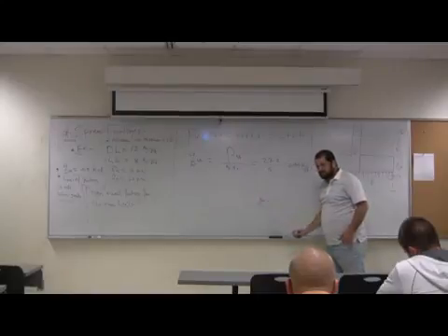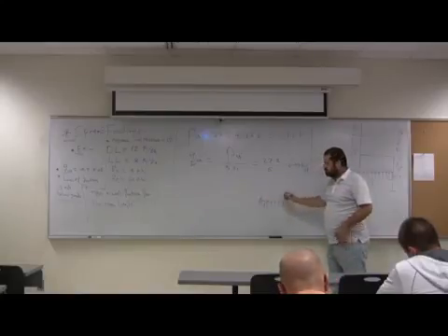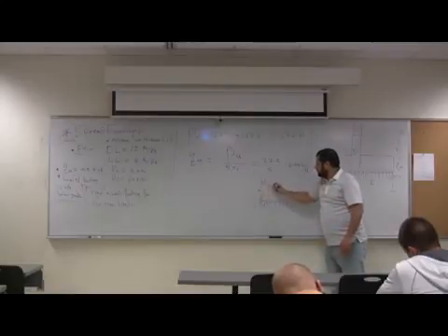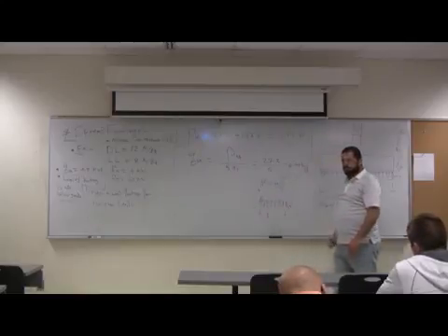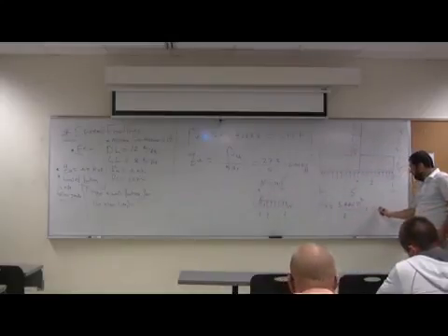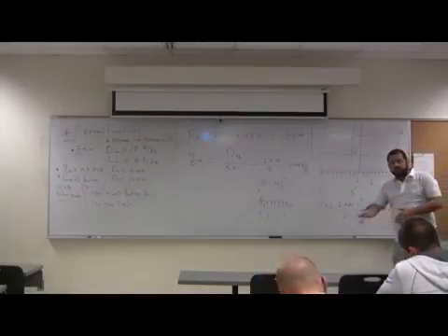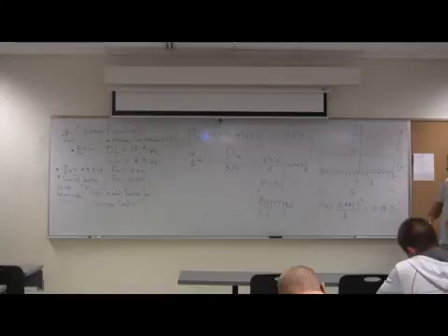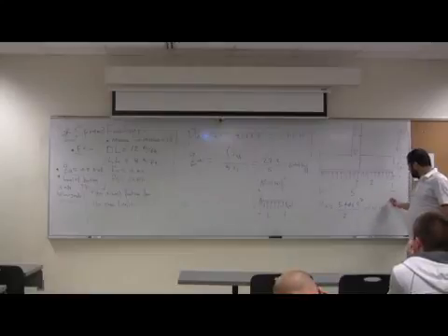The moment here, it's a cantilever, guys. Fixed cantilever with distributed load W. This moment here equals W L squared over 2. This is W and this is L. In our case, L is 2 and W is 5.44. How much do you get? 10.88 per foot. We know that, we're designing one foot strip. So that's the moment. Keep it for now.